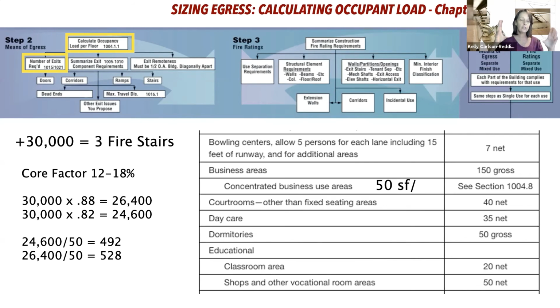It's really assumed that the people who are leaving a floor are entering into the fire stair and beginning to move down, and everybody else is also entering at their levels. It's assumed that they're not accumulating and creating a need for more fire stairs, but they're moving progressively down, and that everybody is exiting through the same fire stair. So you're not going to say, this is a theoretically 10,000 user building, and I therefore need 20 fire stairs. Really, if we stay below that 30,000 number and under that 420-foot height, we have 2 fire stairs.